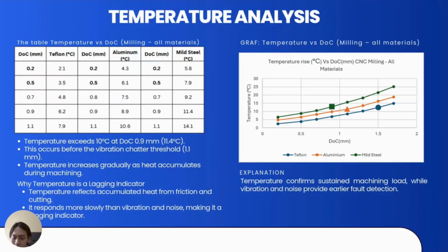It takes time for heat to physically build up, meaning it responds after the mechanical and acoustic shifts have already occurred. While it is not ideal as an early detector, it is crucial for confirming sustained machining instability.